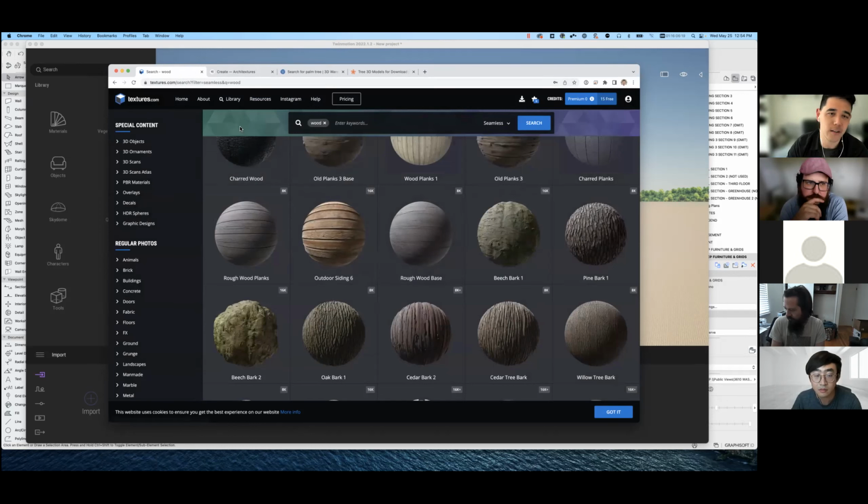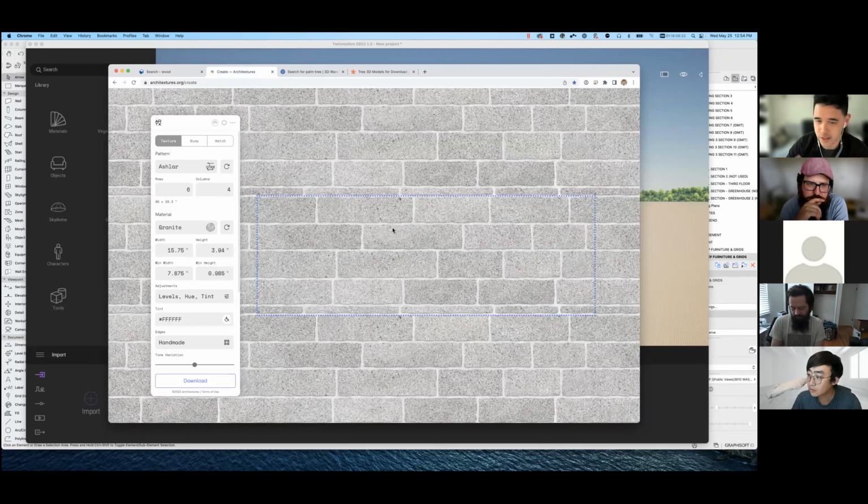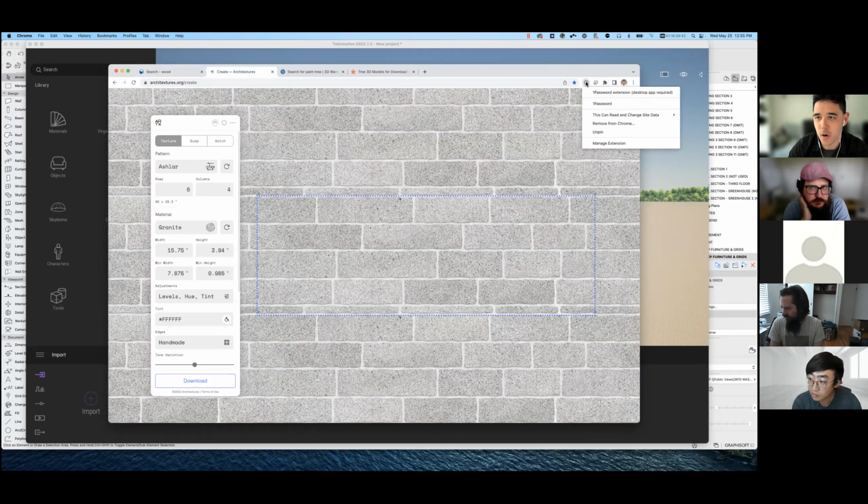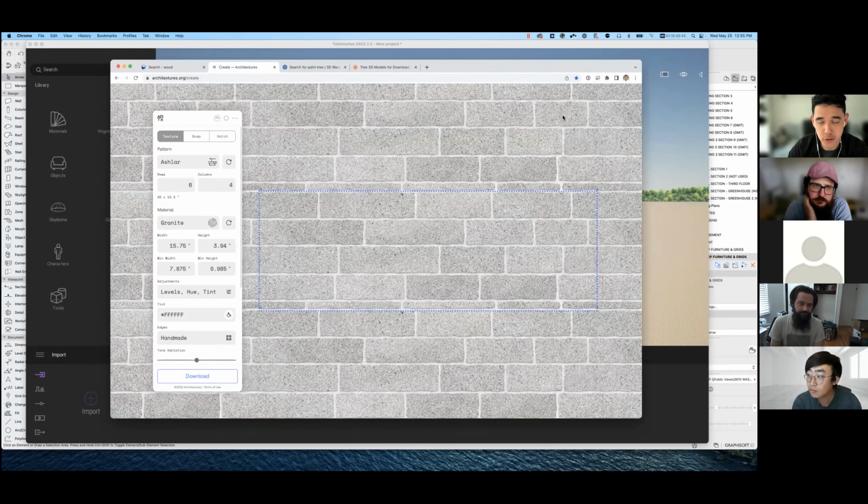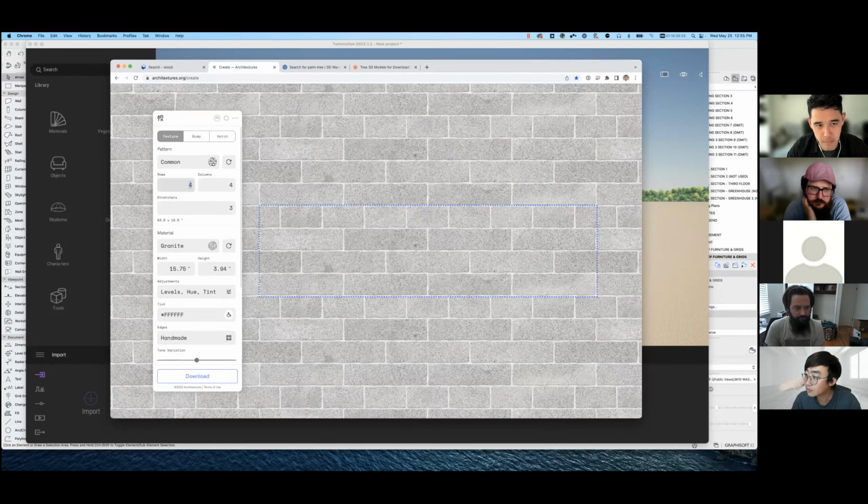The next step is when we get a little bit more custom. We run into this a lot with stone paving, tiles on the inside, even wood board layouts. Let's say we want a custom layout of different size runs of tile going at different thicknesses with a specific joint depth. Instead of scouring the internet to find that exact tile or making one from scratch in Photoshop, we use this thing called Architextures, which Walker Warner has a membership to. If you go into your 1Password, you can ask David Barr to add you to this pro license for Architextures, and this allows you to pick any custom setting of tile bond and layout that we're going to do.